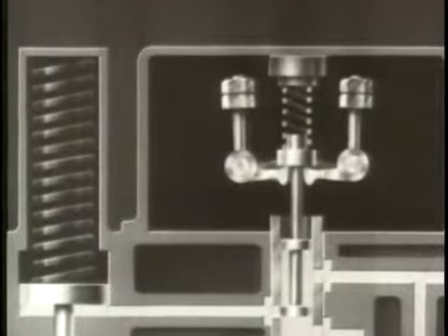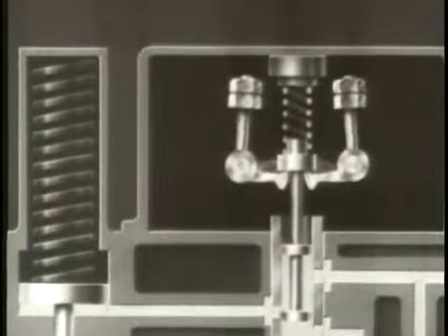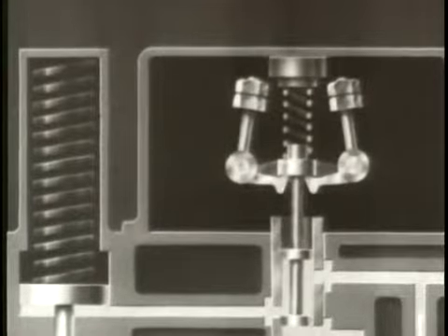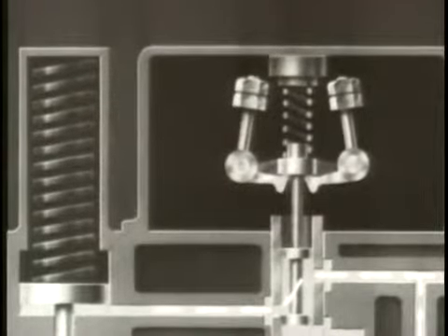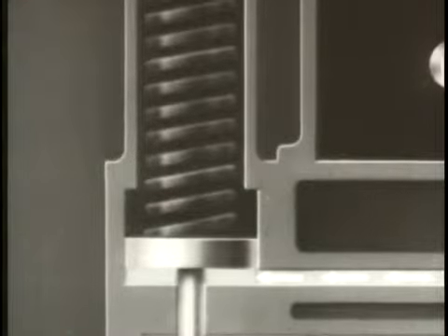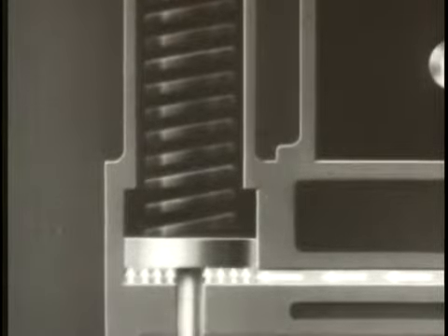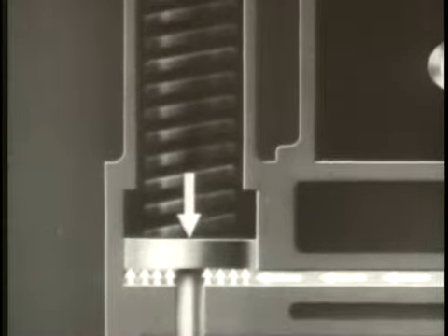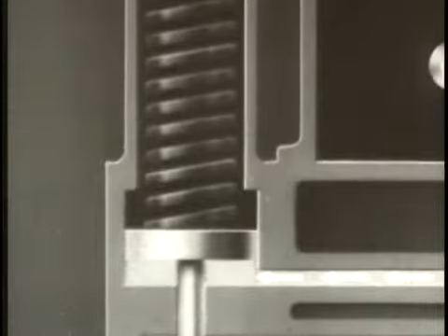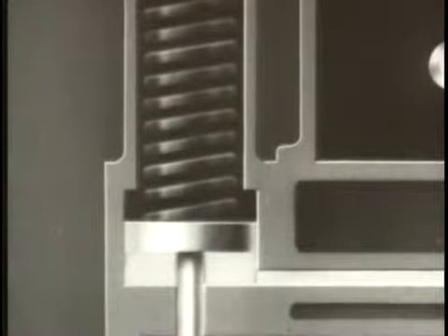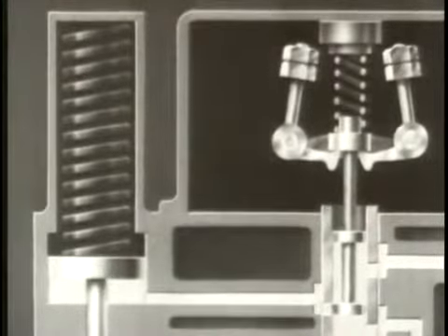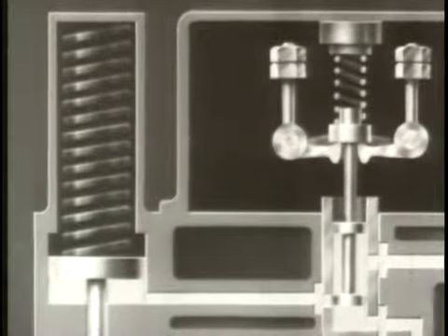If the load increases, the engine slows down, and the flyweights move inward. This lowers the pilot valve plunger, allowing oil to flow through the pilot valve chamber to the power cylinder. This oil, supplied by a pump, is under a pressure sufficiently high to overcome the pressure of the power spring. The power piston moves upward, increasing the amount of fuel injected into the cylinders. Once again, as the speed returns to the set rate, the flyweights resume their central position.